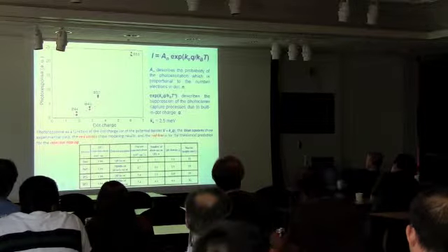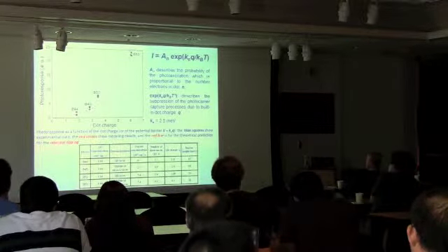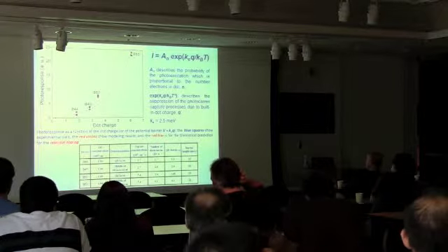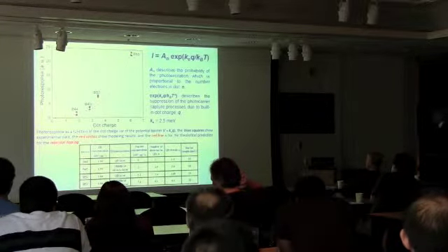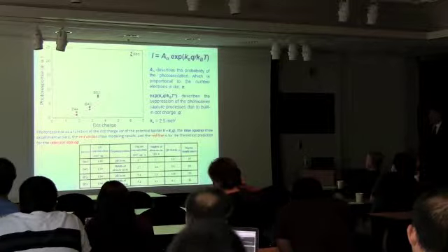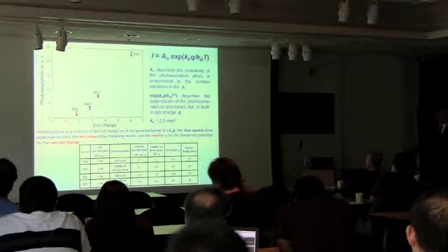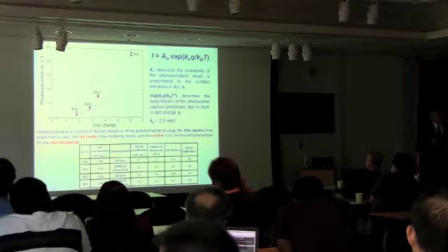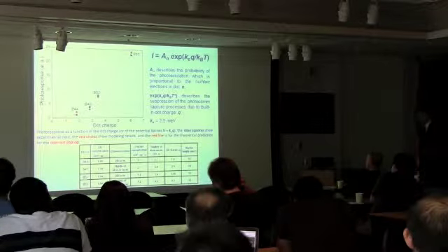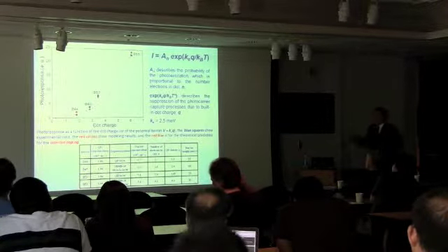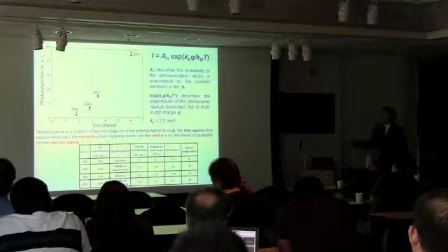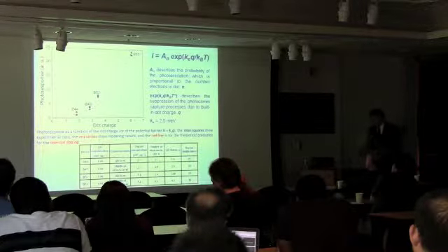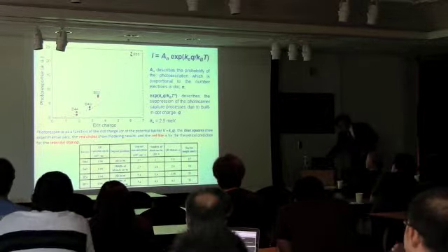And again, the same number of dots, but we have higher doping. Here you have increased doping 1, 2, 3, 4, and as you see, we have a substantial increase of the photoresponse of the detector due to the fact that we increase the lifetime of the carriers due to repulsive potential.